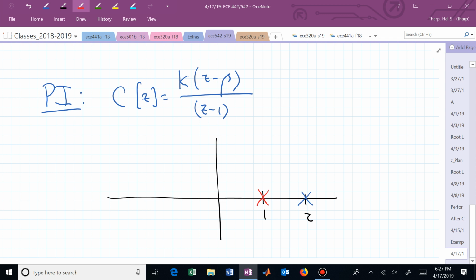Okay, we're still in the restaurant, right? We don't want to walk out of the restaurant and plop the 0 there, do we? Because then our root locus is going to go there, and that's not a good thing, because now we've fixed that pole always outside the unit circle. So we don't want the 0 to be between 1 and 2 on the real axis.